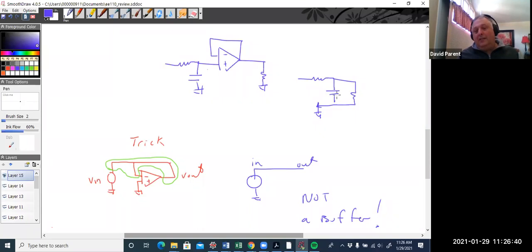And in fact, at DC, this becomes infinite and I get a voltage division. And at high frequencies, it just shorts it. But the time constant would take into account both these resistors. That's a little bit more for them to review, but then we get into the transients where something decays and it takes 5 tau to get there. That's a little beyond today.